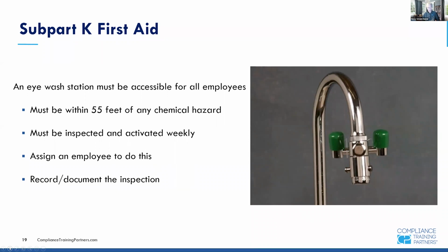And to not do so is one of the top mistakes we see. Many times people will have an eyewash, they haven't activated it in years. You pull the button, nothing comes out but brown sludge, okay? So really, really important to test this.